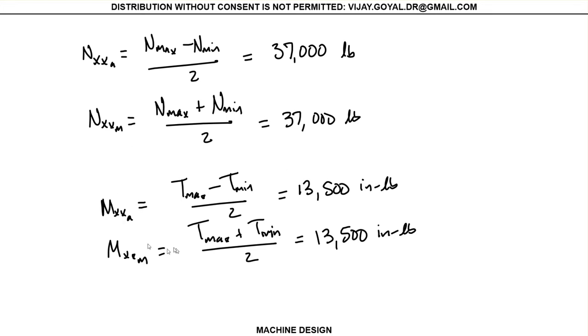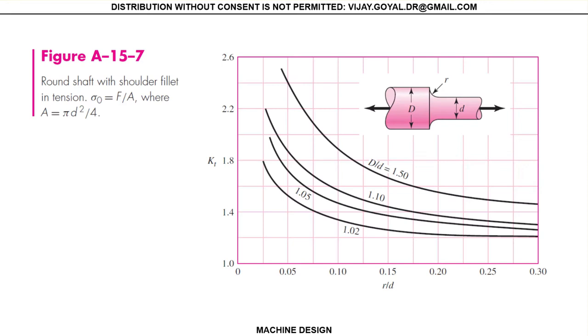Okay, so now that we have this, we have to build our state of stress. But before we build our state of stress, we need to find our load factors. So in our problem, big D over small d, and then I need to know R over small d.